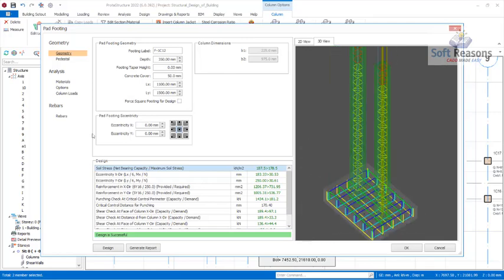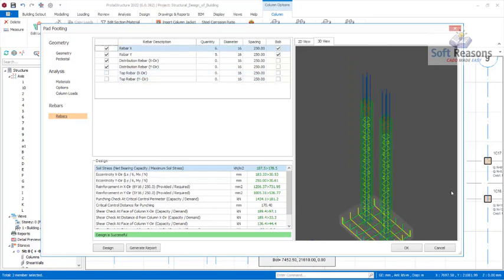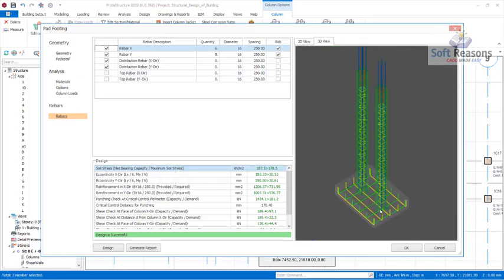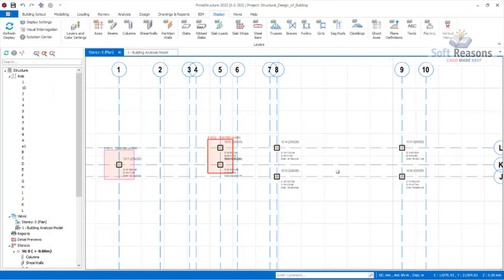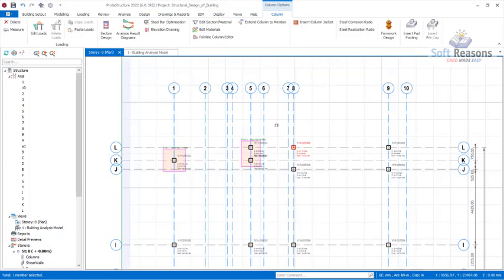So you always come back to the rebars and uncheck these two provisions to have a single reinforced footing successfully. But if you change it in the settings, you wouldn't need to do all of these other settings of removing the top bars. Click on the OK option to have the combined footing placed successfully. So this should be a single footing.